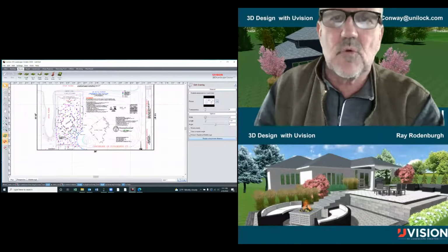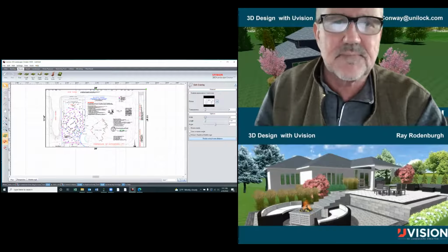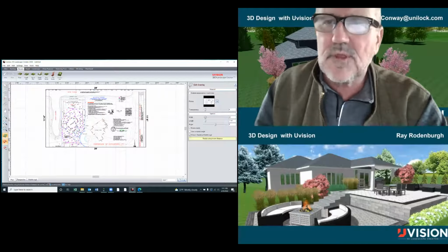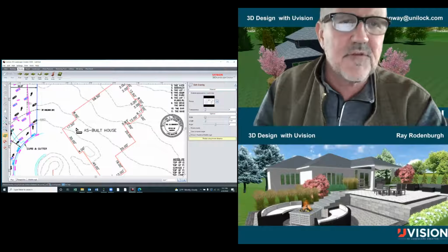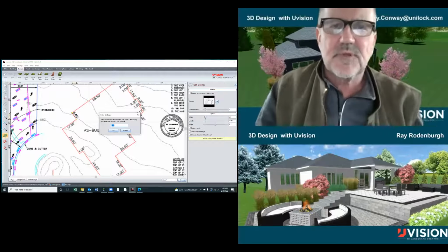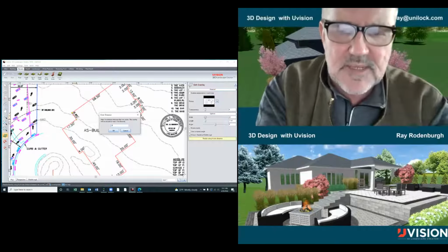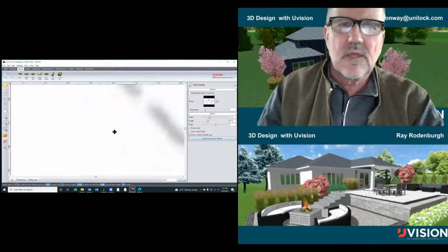Now, what I'm going to do, I've imported this and I resize using known distance. I press that button and I look on the screen and I can see from there to there is 8 feet. I'll turn off the magnet, but if I literally left click, right click, the computer reads it as 4'1" and I'm saying it is 8 feet because that's what I'm reading on the plat.